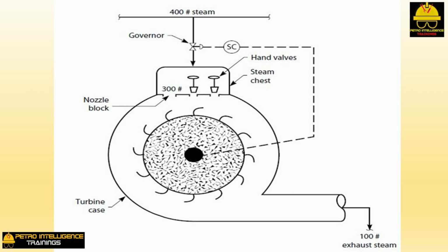The inefficient, irreversible isenthalpic expansion and pressure drop across the governor speed control valve is reduced. The efficient, reversible isentropic expansion and pressure drop across the nozzles is increased. If we now attempt to shut the second horsepower valve, we may be able to save a second 10% increment of steam. But if the governor goes wide open, we will have to open this horsepower valve again. You see, once the governor is 100% open, we will have lost our ability to control the turbine speed. This is no good, because we want the turbine to run at a constant speed.